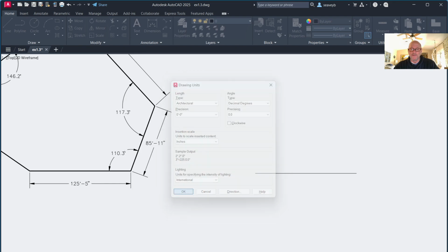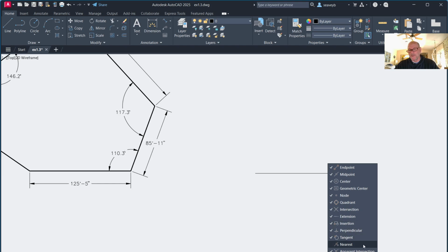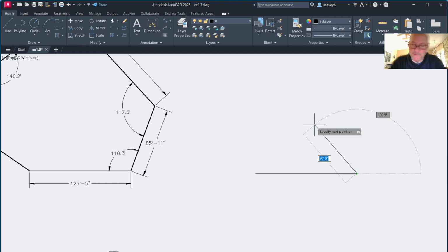Let's see what the dynamic input does with this. So if I start my line again, start at the end, snapping. So I do have my snap settings on. Basically, I have every snap setting except nearest turned on. So we'll see what that allows you to do. So anyway, starting the line there, it still doesn't respect those units at all. So that unit setting for the direction doesn't really help in the dynamic input. Now, if I didn't have dynamic input turned on, I suppose I could set that angle. Well, we can hit F12 on this tablet. I can, let's see, there's F12.